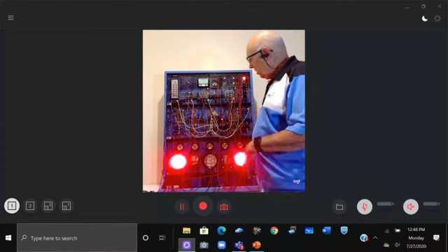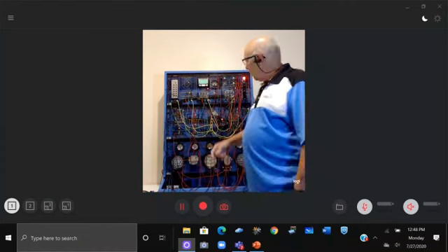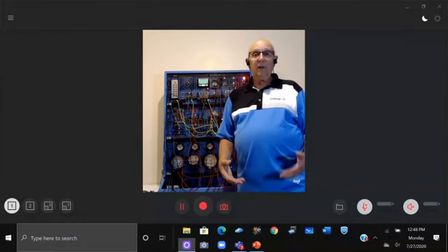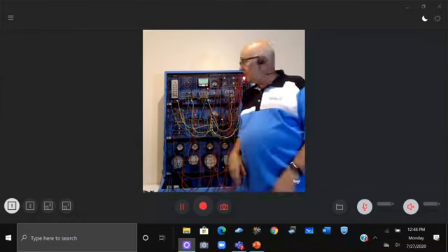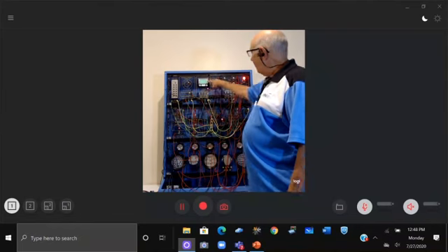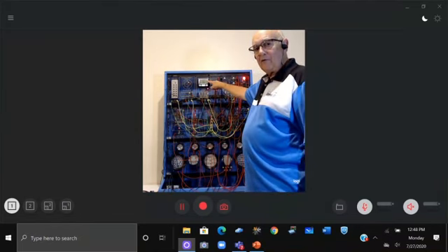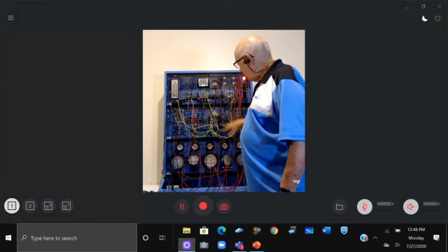So in other words, it wasn't a wake-up signal. It was the signal for the hazard lights because they have to be functional, and that's what actually turned on the system. If I turn that off, this is going to go back to sleep. Now, it may take, there's your 4 or 5 seconds again, okay? And then everything goes to sleep.